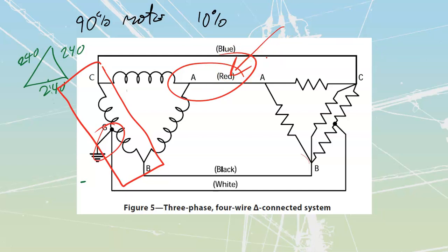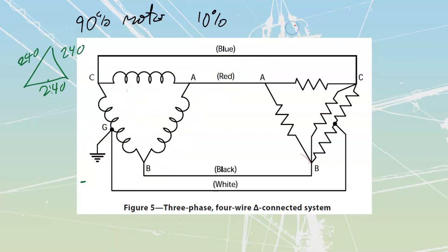You cannot buy a three-phase panel, put that three-phase panel in, and then connect A, B, C and the neutral into that one, because what actually happens is if I were to go back to this one over here, calculate our voltages, if I were to go to the value of 240 volts that we have for each of these, I would see that half of that would be 120, half of that would be 120.